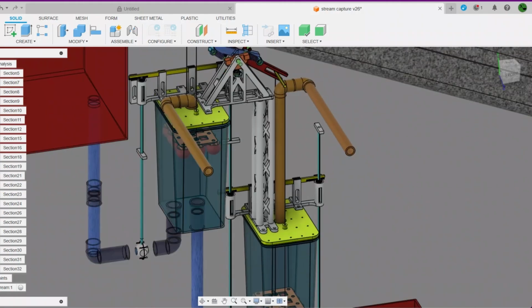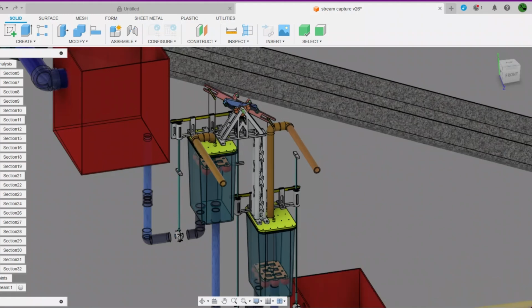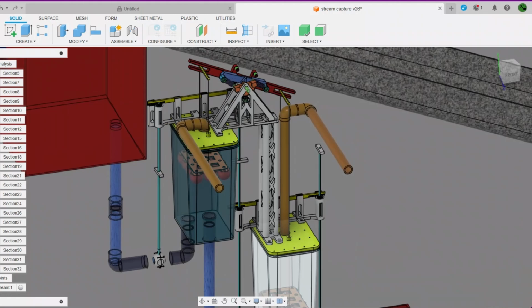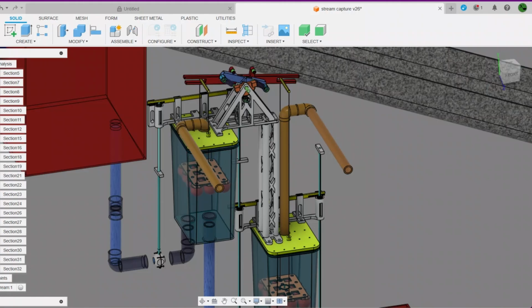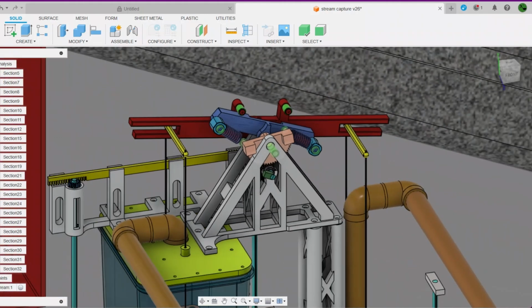So now water will come out of here and into chamber 2. This one's closed, so water can't escape, so it just stays in chamber 2. So now we've got the water difference. So now this one's going up, and this one's going down. Now again, watch this. Once this one pushes this far enough down, the springs will push this up, which then translates through here and then down through here.